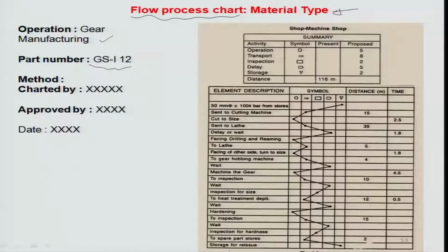some kind of process treatment, let us say heat treatment of the surface, so that there is enough mechanical strength so that gear meshing can be initiated between these two gears. Then, for example, inspect at various levels what the material property is, what the hardness is based on these materials, and then storage spaces can be earmarked for storing the part for further use.